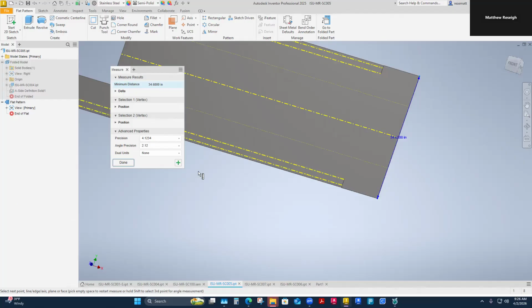Then you have to go into your design and decide where to put seams. If the part was 15 feet by 72 inches, I'm not going to make them buy a piece of sheet metal like that. I'm going to have to determine what my manufacturers can build with, what size sheets we have on hand, and what we regularly stock, and design with those constraints in mind, right?